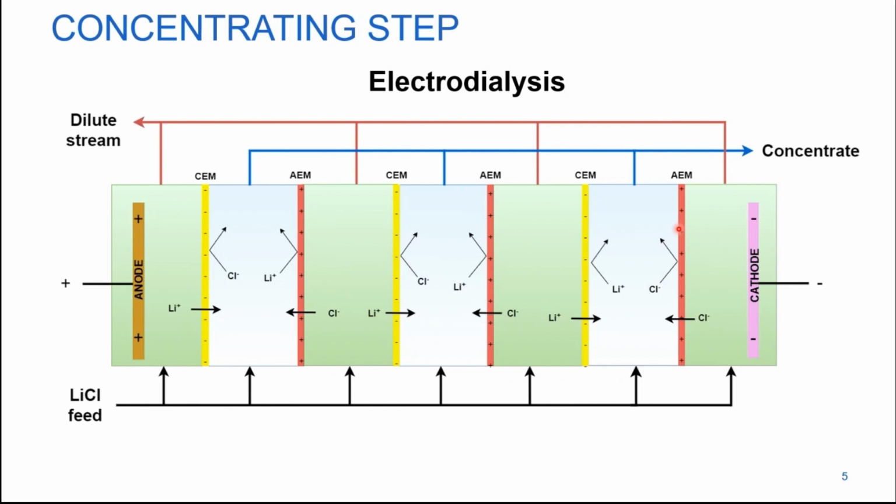Good. The first application or possible configuration of an electrochemical system to use in the lithium refining business is electrodialysis. Here, in this case, you're not just going to have one membrane and two electrodes, but you're going to have, as you see, a lot of different membranes, cation and anion exchange membranes that are alternated, and you will have one anode and one cathode. And the amount of membranes in between these two electrodes can be sometimes up to more than 100 membranes.